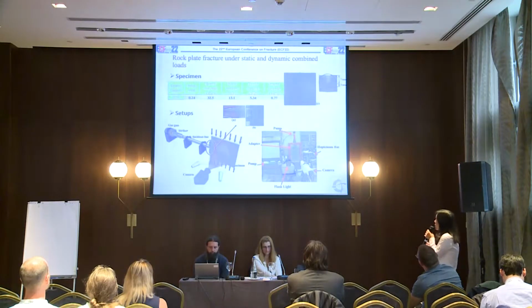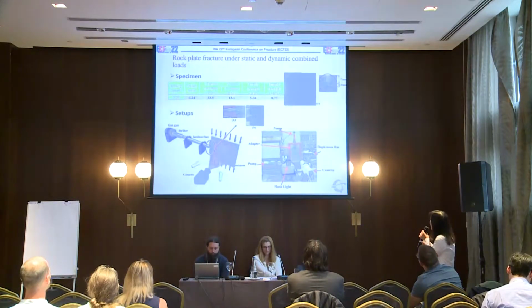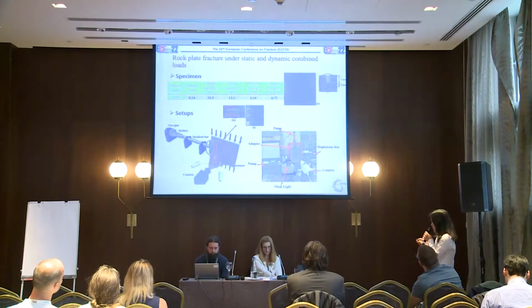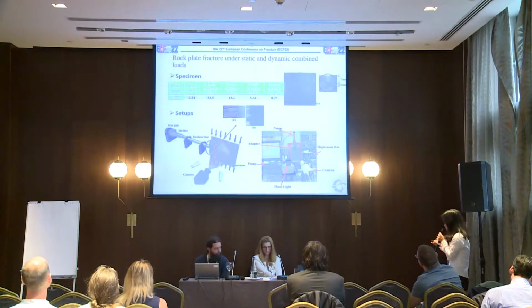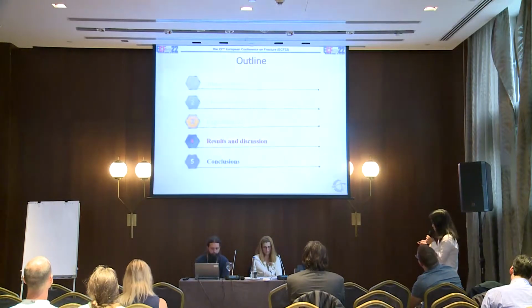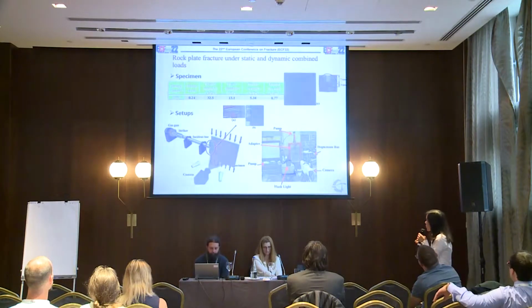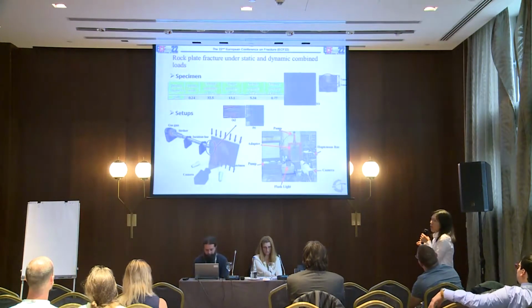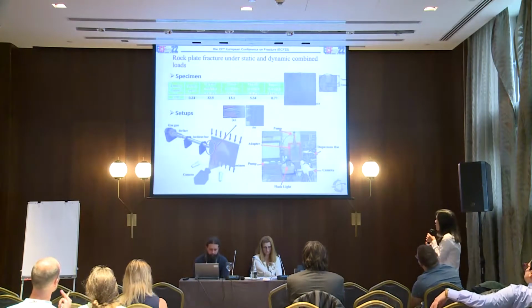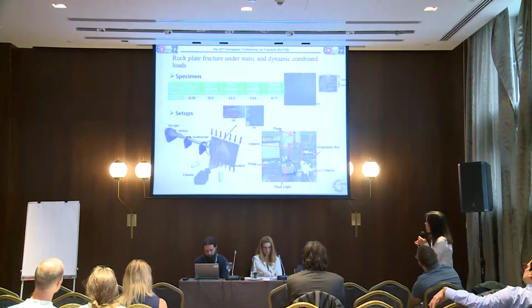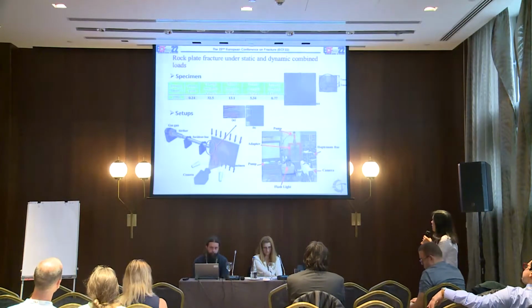Experiment. We use this rock plate. It's about 350 by 350 millimeters. The parameters are here. The dynamic loading was exerted by this split Hopkinson pressure bar, which includes a gas pressure gun, a striker bar, and an incident bar.